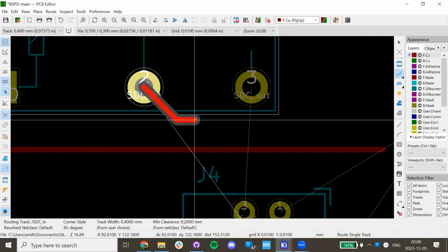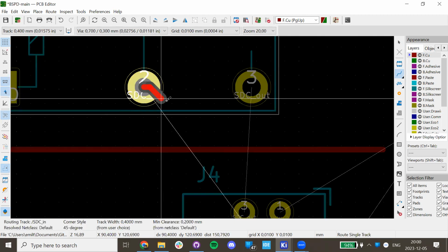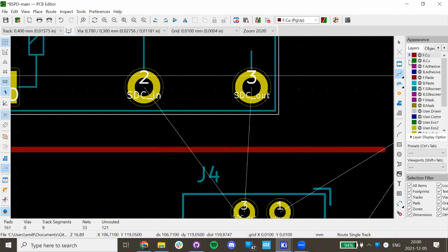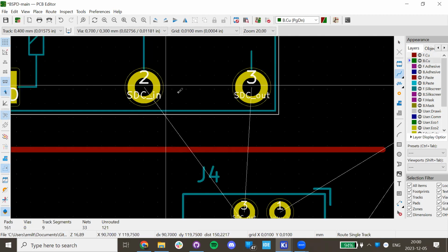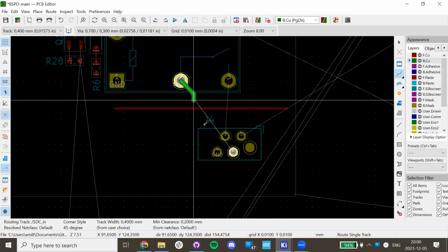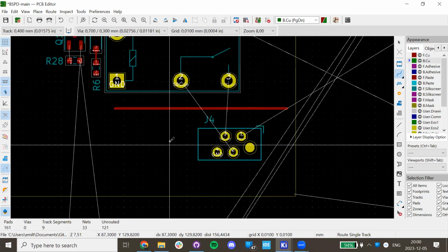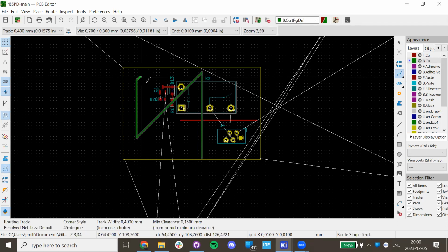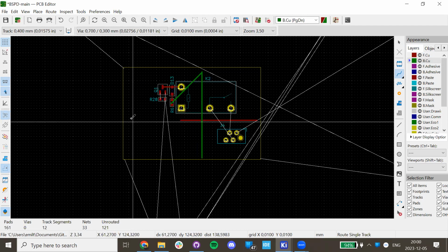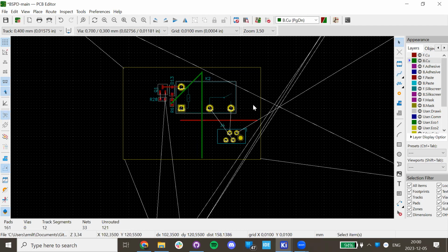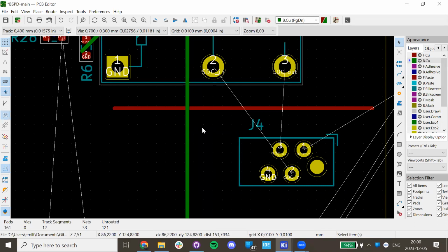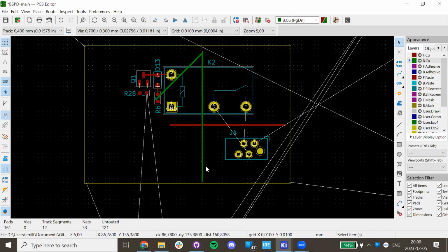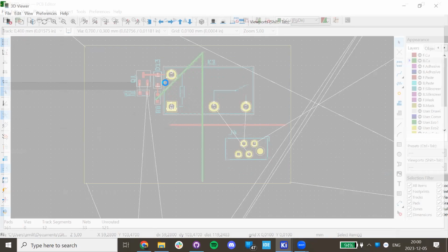So you want to reduce the amount of traces on the back plane. Like I can, whenever press here on the back copper layer, and I can start routing from the back copper. And then you see how I can just go straight through it. But what happens if I have a bunch of wires on the back layer here? Well, suddenly, in this case, for example, if I have ground here and I have a ground component here, what happens with the current? I have to think always, this part is gonna be some net, maybe 5 volts. So this isn't ground.